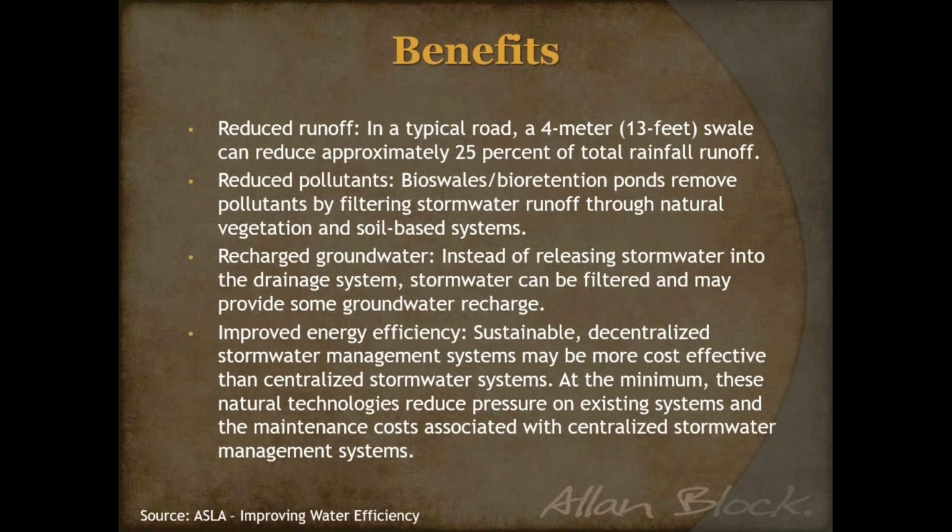So if you can have it go into your system and capture it, now you've got less runoff that you've got to worry about going to your neighbor's property, or about handling and satisfying the permit requirements for the land development in the first place. We also know we're doing a good thing for the environment, right? We're grabbing that water and we're reducing the pollutants. So the bioretention is going to remove the particles.